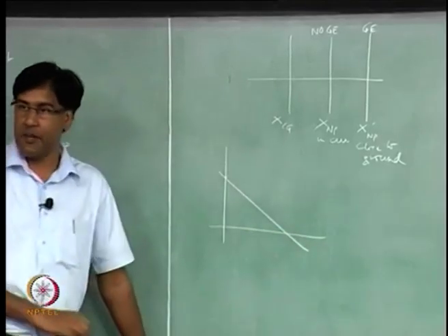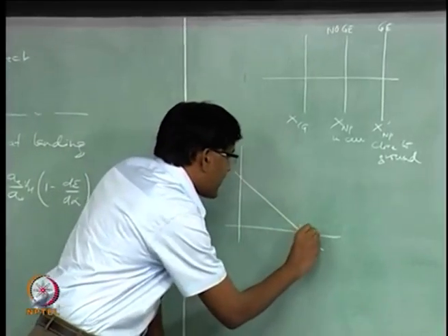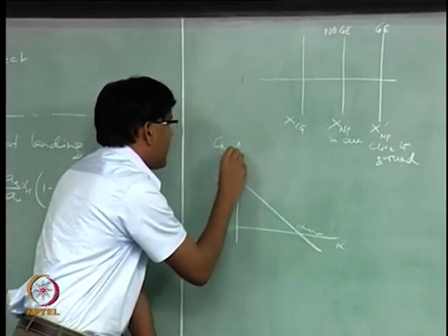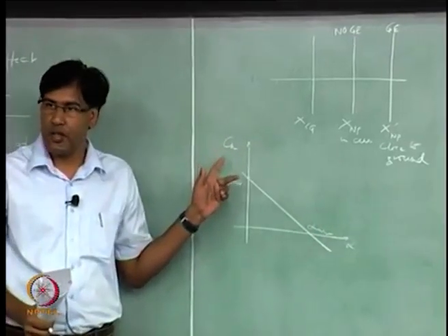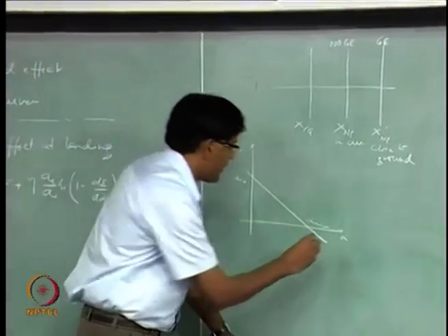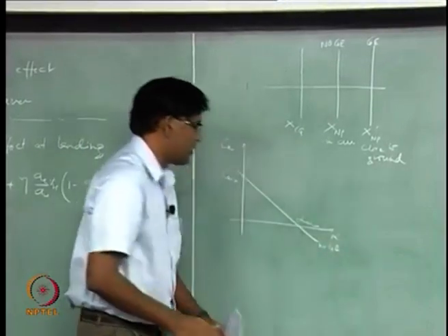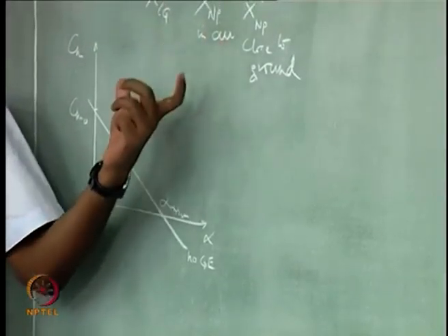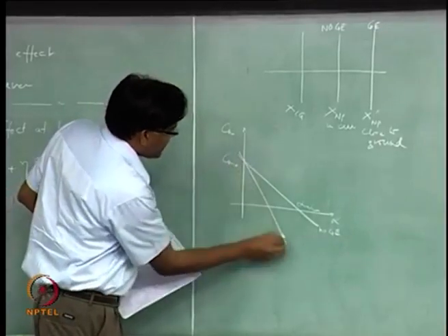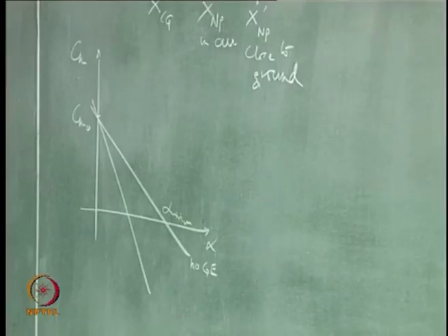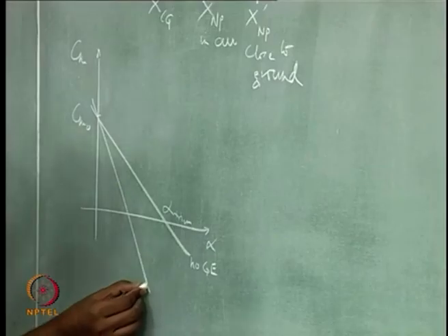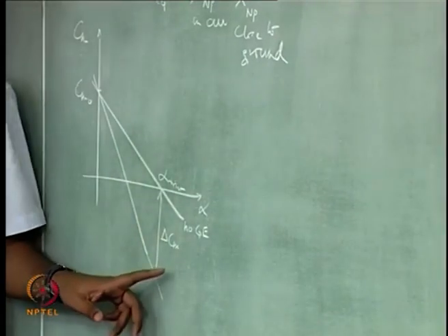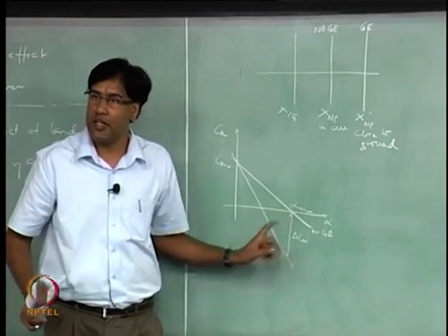So, you are able to trim at some angle of attack in air, right. This is alpha trim, this is no ground effect. What happens when I am including the ground effect in this? This curve will have a steeper slope, right. So, that means you have to make up for this extra delta Cm to trim at this alpha, isn't it?